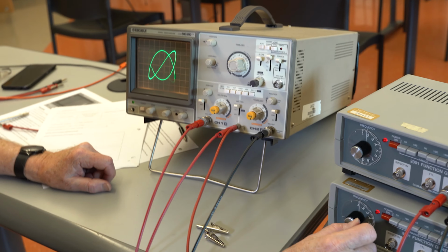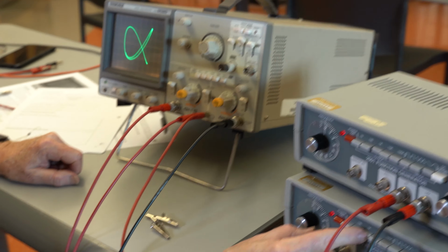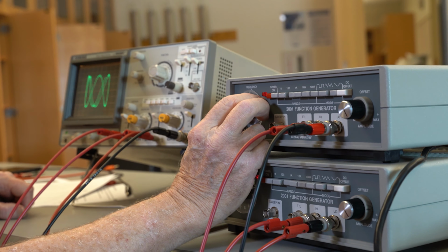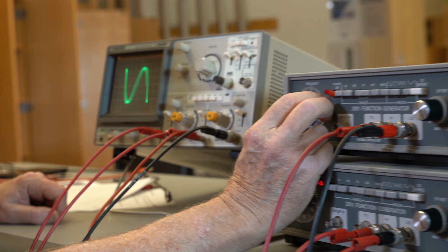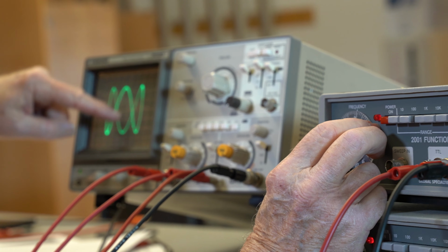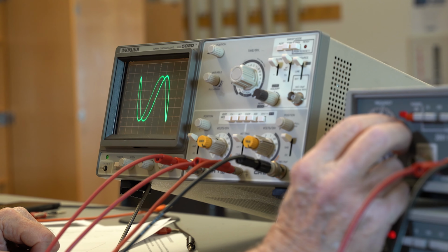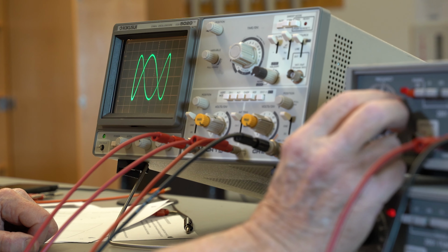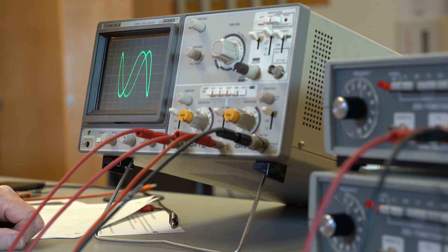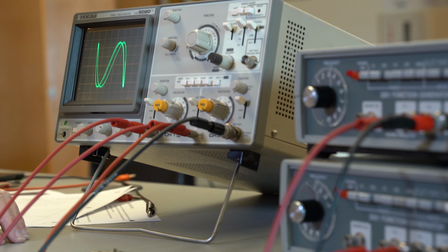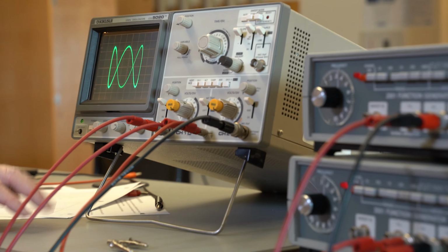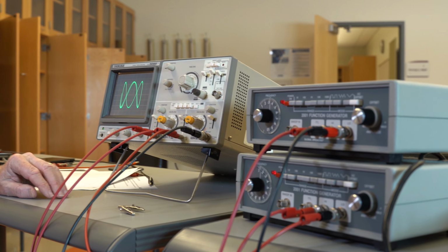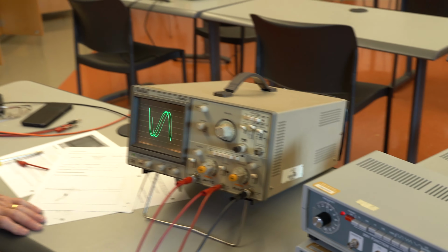Let's see if I can get the 3 to 1. Okay, so we've got, okay, 1, 3. There's 3 to 1. Notice there's 3 peaks vertically and 1 horizontally. So you can see what the ratio is between the 2 frequencies of these frequency generators just by watching the Lissajous pattern. And you can get more complex patterns as well. Okay, that concludes our oscilloscope